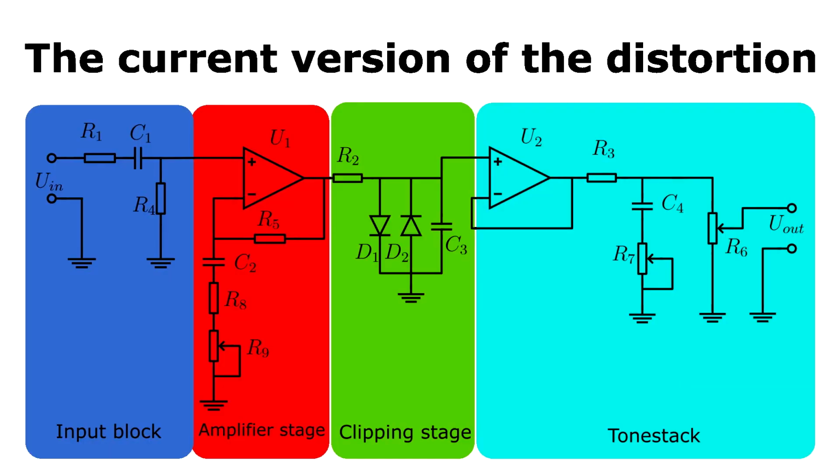The frequency balance is better than the flat fuzz from the previous video, but to be honest, I don't love the sound of the paired diode distortion. Too many even non-linearity products, the long harmonic spectrum. I'm starting this series of videos to demonstrate a schematic that produces sound without annoying harmonics. In the next series, we will explore nonlinear wave shaping and how different types of diodes and transistors can affect the signal distortion. And finally, you get the first applicable variant.